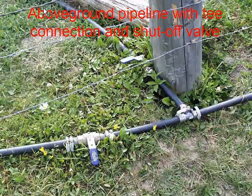The pipe color here, this HDPE pipe, is black. Sometimes these pipes will be white because it'll keep the pipe cooler, but a lot of times you'll have grass or vegetation that grows up a little bit on your fence rows, and if you put your pipe down underneath that vegetation, as the vegetation grows over it, that actually helps to cool your pipe system, which is usually a good thing because cows would prefer to drink cooler water than warmer water.